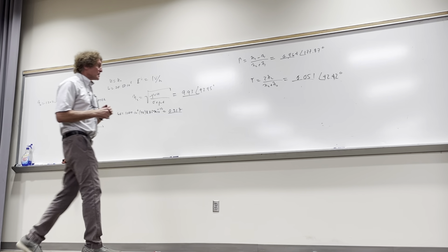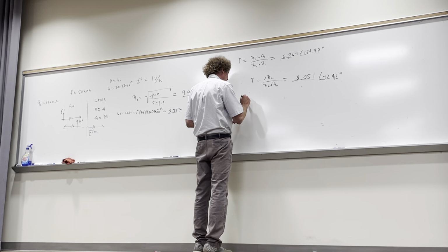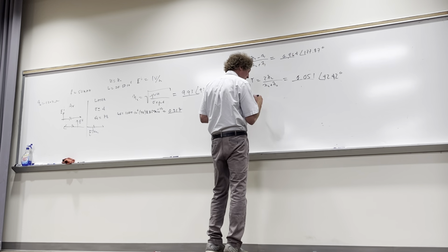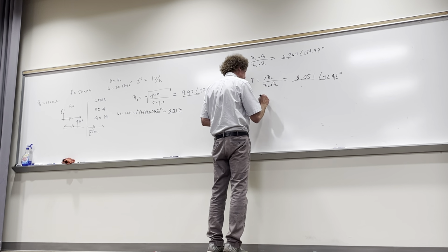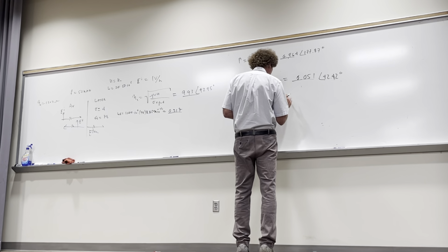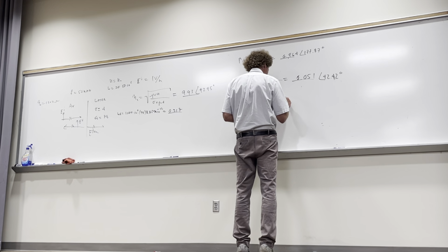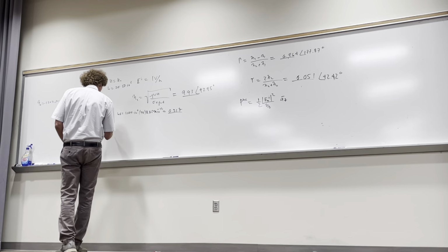reflected. So the incident power would be equal to, because it's in air, simply 1/2 the magnitude of E naught incident squared over eta naught. And if you want to be frank about this, you can put it in the a_z direction if you assume this is going to be the z direction. You don't have to do this.